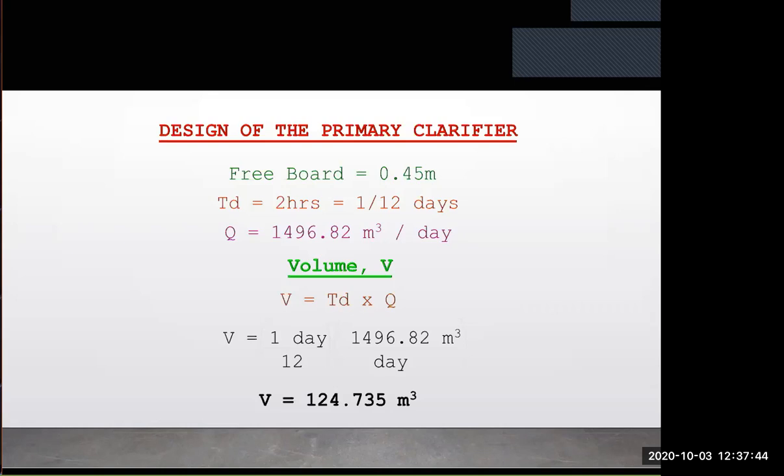Okay? So, dapat your freeboard must be appropriate with its purpose or its function. So let's say that the freeboard is equal to 0.45 meters and then the detention time is 2 hours. I'll give you this one anyways when you do your plate.